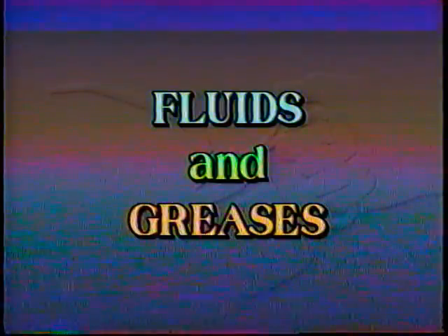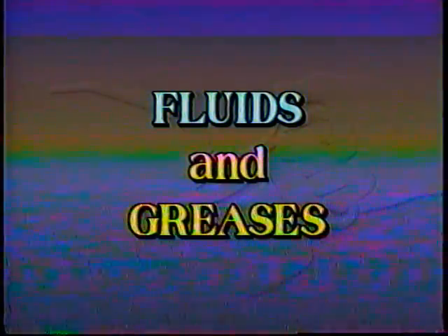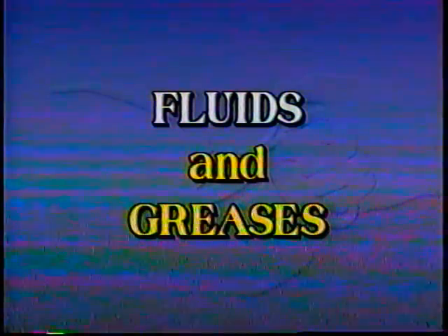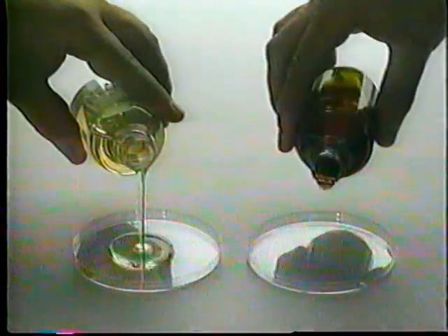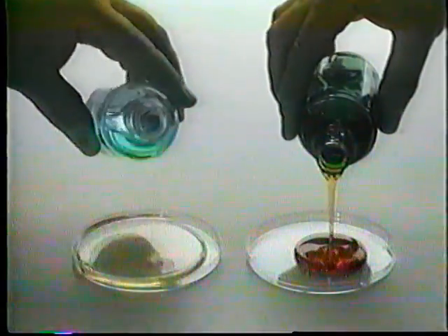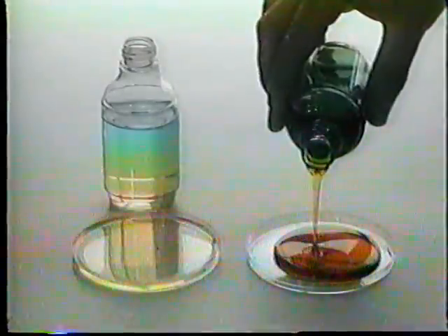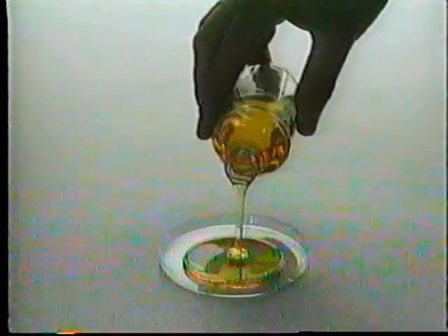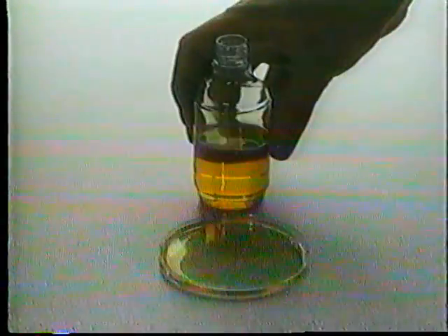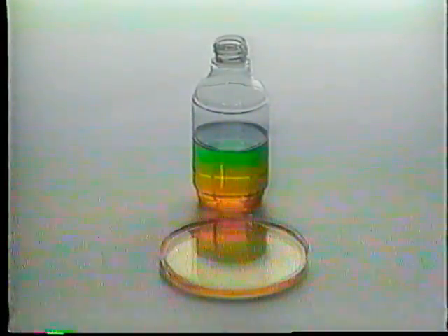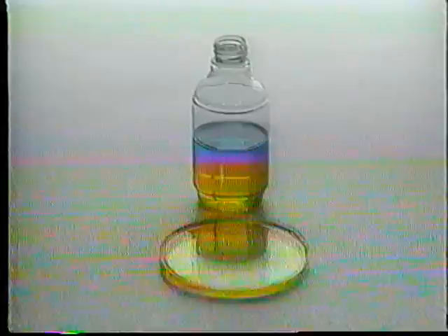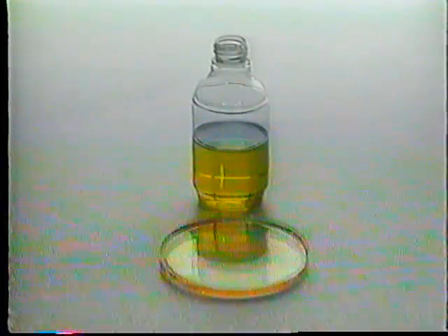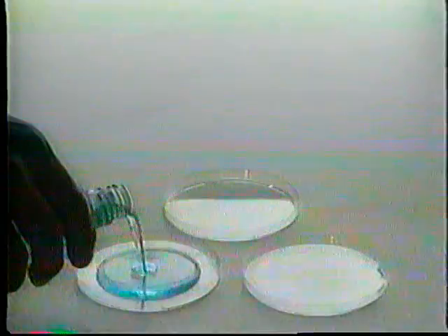There are two major kinds of lubricants, fluids and greases. Fluid lubricants are classified according to their source of origin. Mineral oils are made from refined petroleum and come in a wide range of thicknesses for different applications. Biodegradable oils are made from either vegetable oils like rapeseed oil or from synthetic esters. These are used in situations where other types of oils might cause environmental damage.